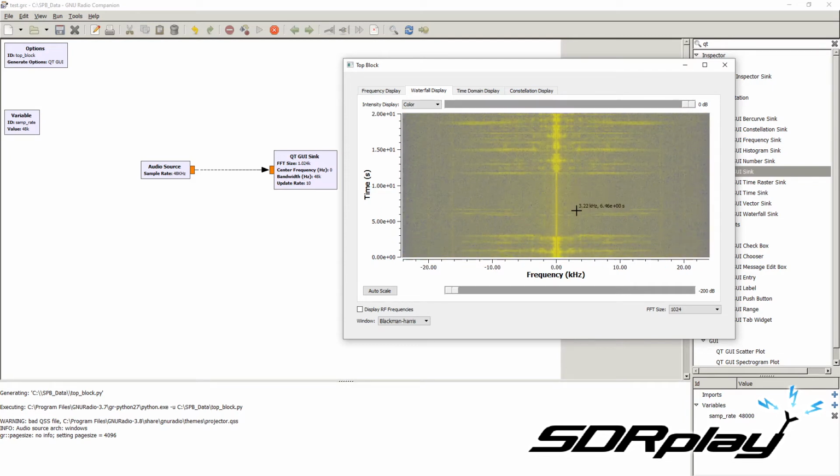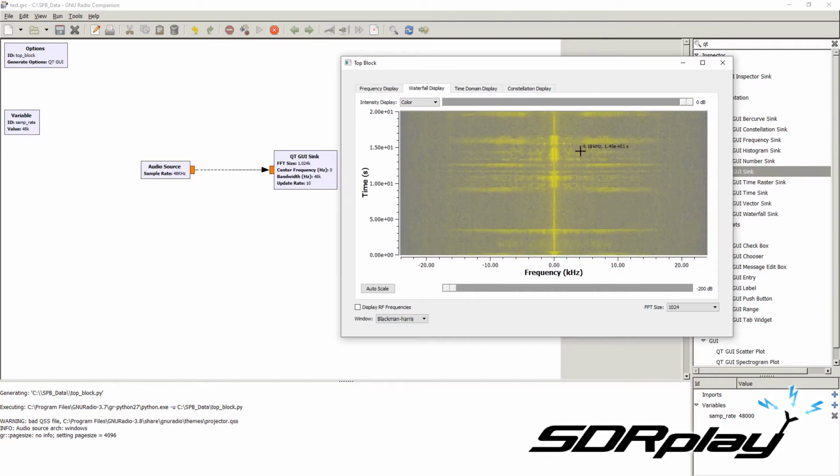So it would be a good idea to reduce the sampling rate, so to reduce the bandwidth, so that we only use 2 or 3 kilohertz or something like that. To do this, we can use a low-pass filter. What the low-pass filter does is suppress the bandwidth of signals of a frequency higher than the frequency we choose.